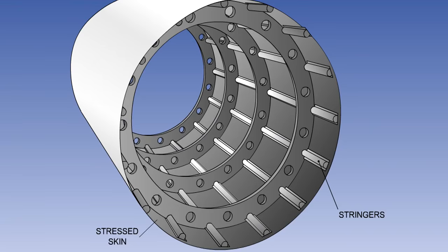As aircraft became larger and the air loads greater, the pure monocoque structure was found not to be strong enough. Additional structural members, known as stringers or stiffeners, and longerons are added to run lengthwise along the fuselage, joining the frames together. The light alloy skin is then attached to the frames and stringers by riveting or adhesive bonding.